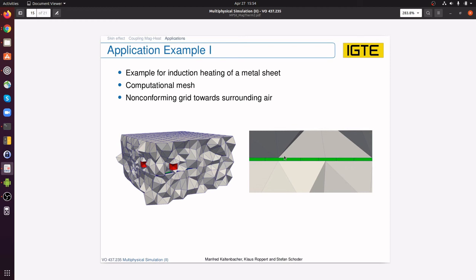you need pyramid elements to connect hexahedrons and tetrahedrons, because hexahedrons at each surface have 4 nodes. Tetrahedrons on each surface have 3 nodes. So how do you connect these two element types? Via pyramid elements that have 4-node faces and 3-node faces.